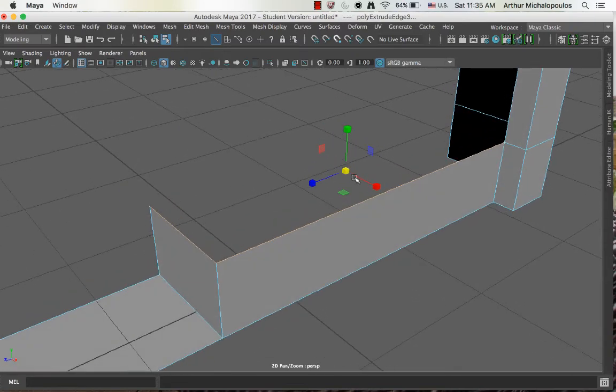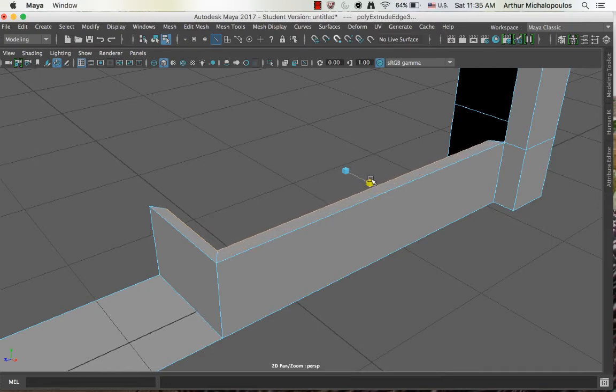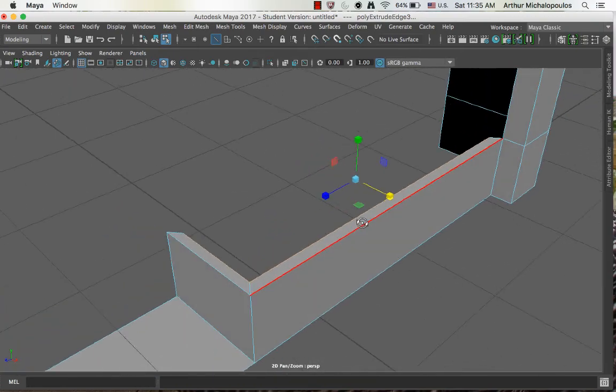And from the center of the scale tool, the handles here, click and drag to the left. And maybe click on the x-axis so you can actually see what's happening. It's scaling those two edges, but because they're where they are, it effectively scales it in. So what we're doing here is creating a little bit of an edge, or a ledge rather, for our shop window base.